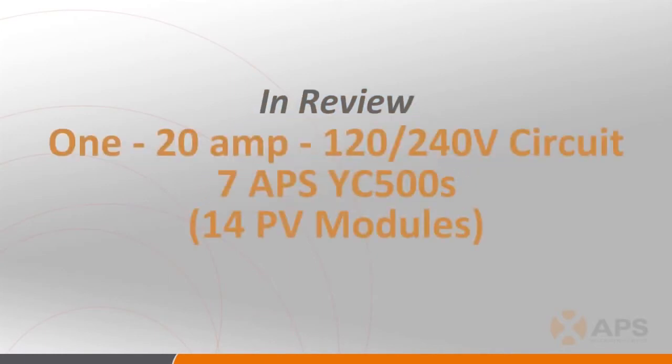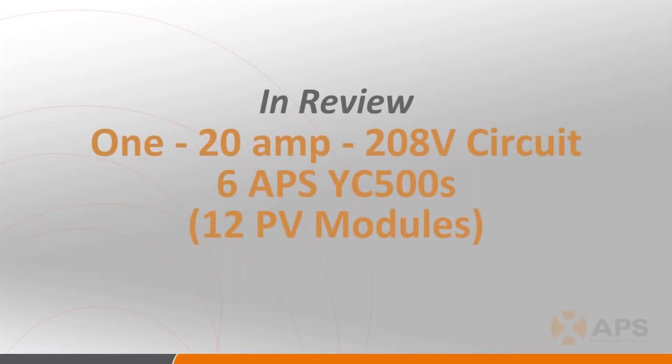Again, as review, the maximum number of units per 120/240 volt, 20 amp circuit is 7, or a total of 14 PV modules, and the maximum number of units per 208 volt, 20 amp circuit is 6, or a total of 12 PV modules.